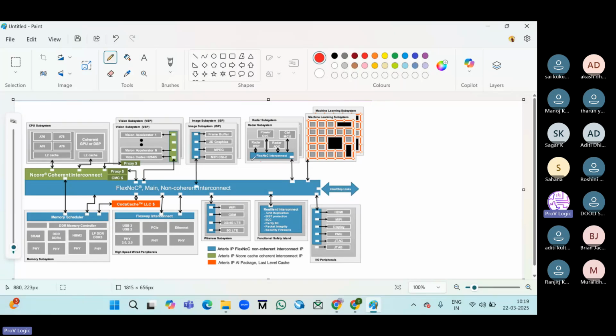Yes, actually, this SoC is a basic common system on chip design. But if you go to a mobile SoC, obviously every SoC is different. A mobile SoC is different, and coming to laptop system SoCs, everything is different. But whatever we are saying here is just a basic idea. Internally, if you go to the exact SoC the industry puts out, it has a lot of external blocks: debug units, DFT blocks, video related blocks, and even a scalable fabric and data fabric control hubs.